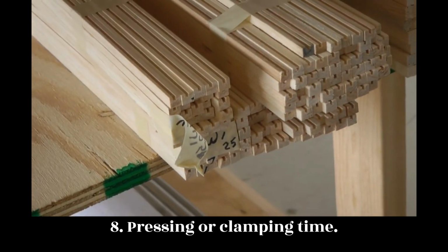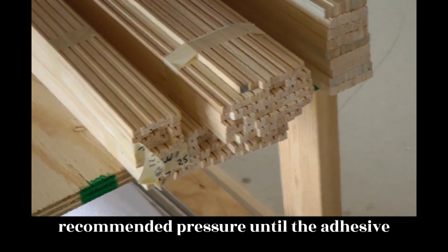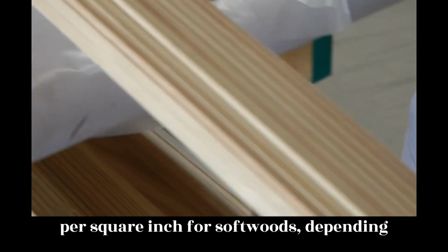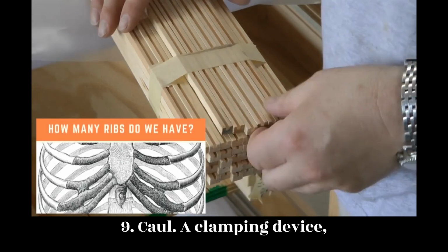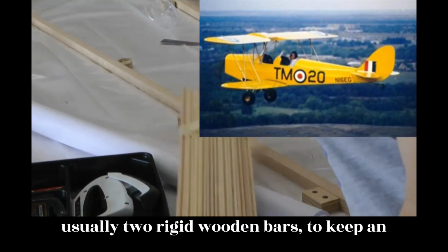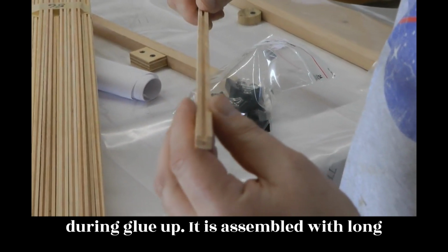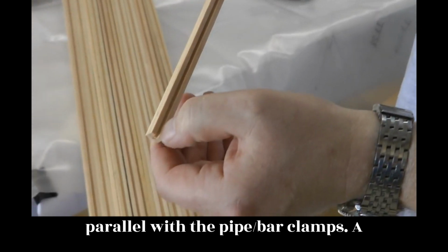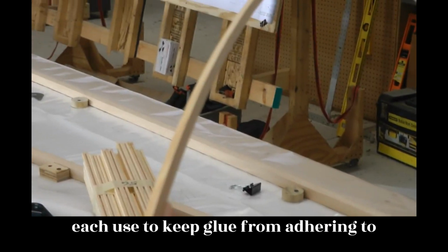8. Pressing or clamping time. Time during which the components are pressed tightly together under recommended pressure until the adhesive cures, which may vary from 10 to 150 pounds per square inch, PSI, for softwoods, depending on the viscosity of the glue. 9. Caul. A clamping device, usually two rigid wooden bars, to keep an assembly of flat panel boards aligned during glue-up. It is assembled with long bolts and placed on either side of the boards, one on top and another below, and parallel with the pipe/bar clamps. A caul is usually finished and waxed before each use to keep glue from adhering to it.